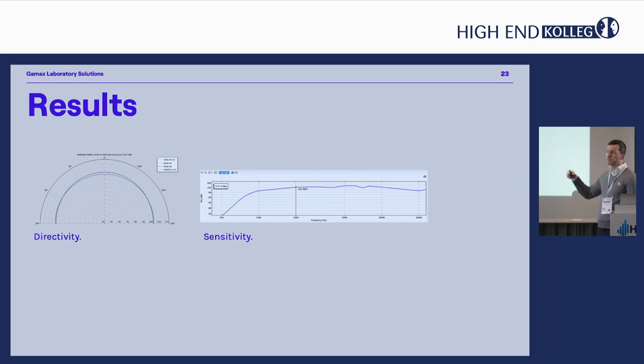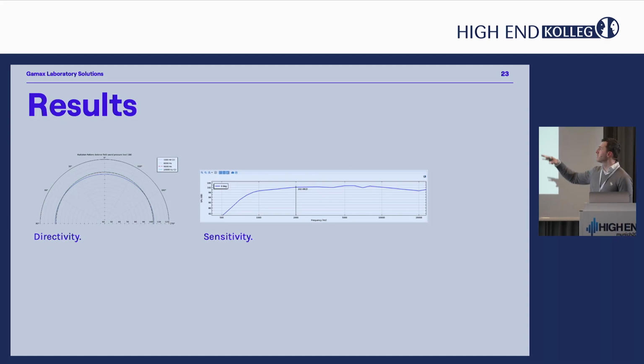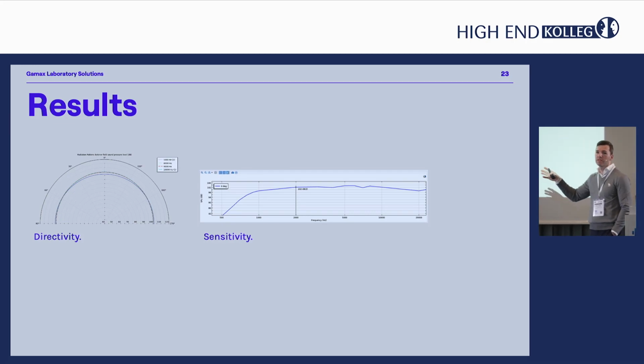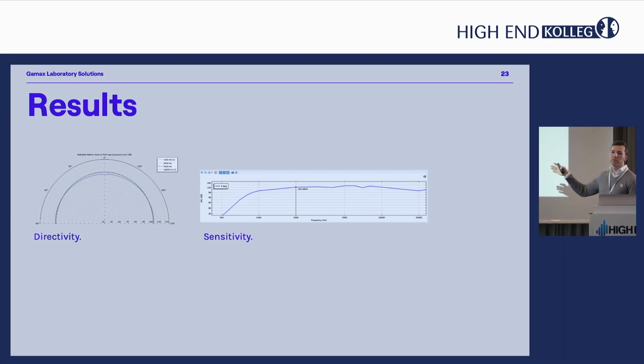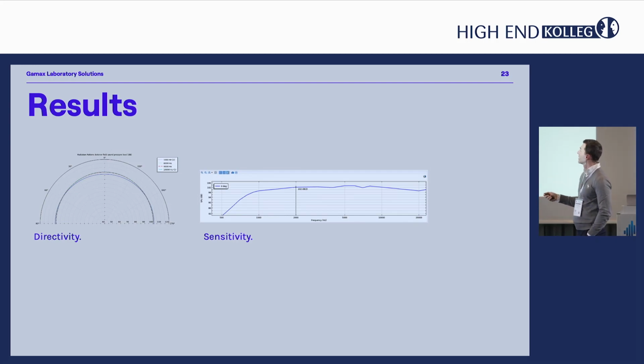And of course, when we have the measurement data, we can match the properties, especially for the suspension. We can check the validity of the 2D model. So what's the validity range? There are some assumptions for the 2D model, but we can have an understanding how the tweeter will behave for these properties.